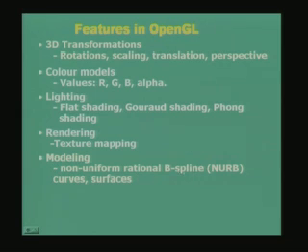We talked about cubic spline and Bezier curves, a combination of that, where a spline that uses the Bernstein basis is called a B-spline. Okay. So, we have these NURBS as curves and surfaces, and that could also be used to define your primitives. Okay. And the data could consist of vertices, colors, surface normals, texture coordinates, edge flags, which could be associated with either a vertex or a particular curve or a primitive.